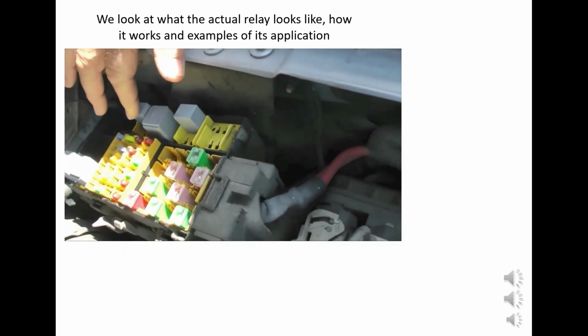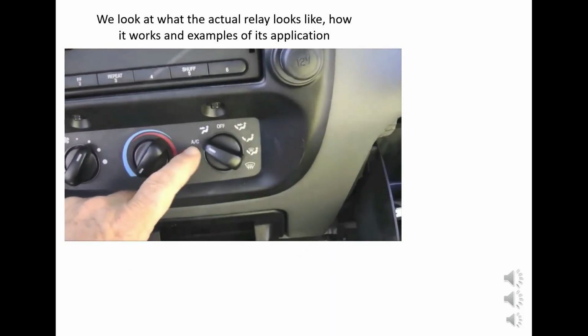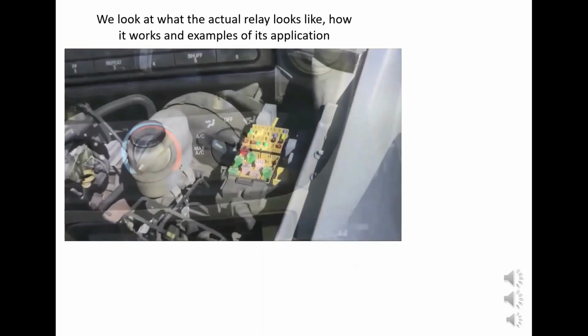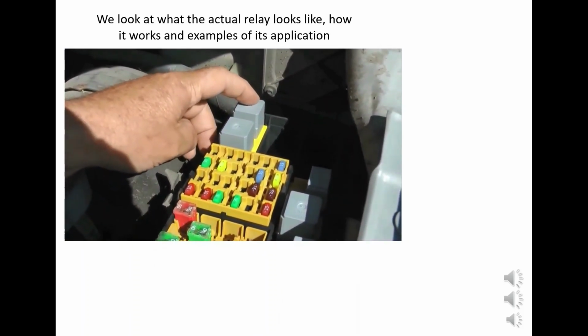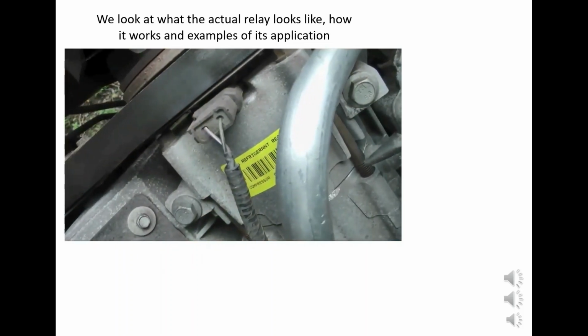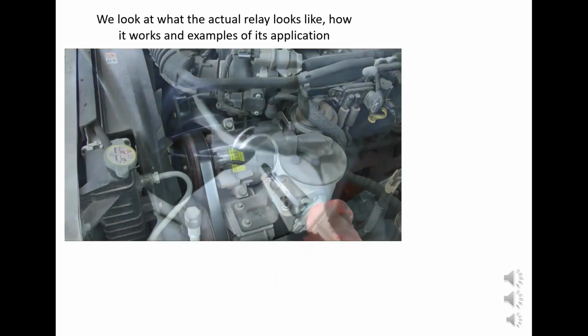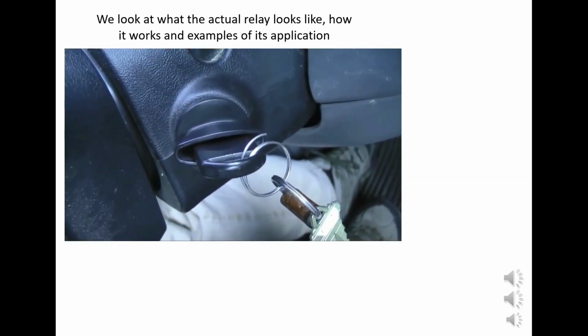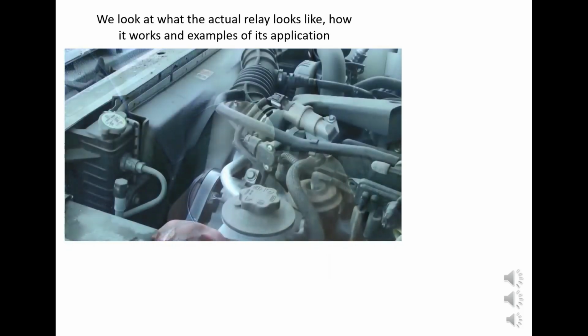These devices are relays. Turn on the air conditioning in this truck, and the small current from the dashboard switch energizes a coil located in this relay. The coil pulls heavy-duty contacts together, contacts capable of handling the large current needed to engage the air conditioner. The electric starting motor in a vehicle uses a very large solenoid relay system that is activated when you turn the ignition key. Without a system like this, the small switch on the steering column would melt.